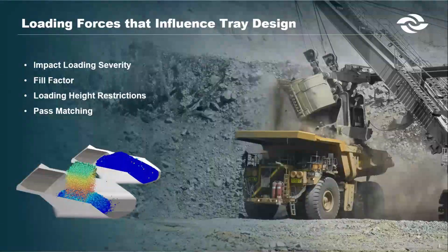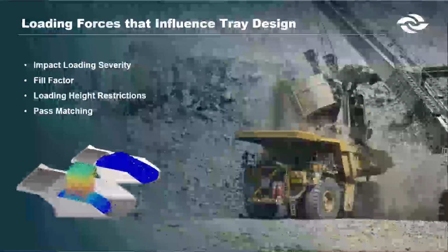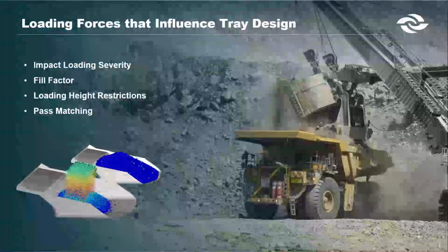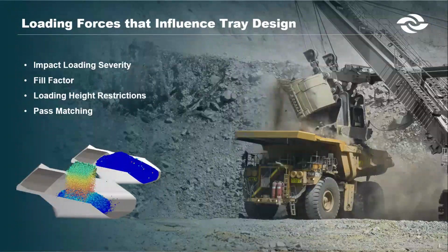Now, let's address the reality of overloading. It happens, and that is why we design in line with OEM policies. The 10-10-20 overloading policy is not arbitrary. It protects operators, machines, and mines. The average payload must stay at or below the target payload. Up to 10% of the loads may go up to 110% of the target, but no single load may exceed 120%. Beyond that, you are outside safe design limits and you're compromising the truck's life and the operator's safety.